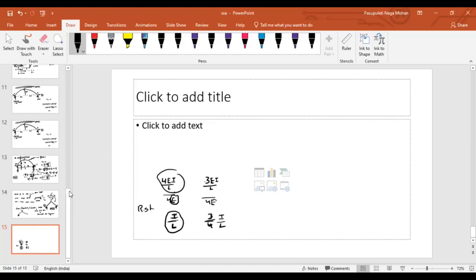I depends upon the cross section. E depends upon the material. In general, the material is constant everywhere; most of the time you will cast with the same strength of material at a particular level of floor. But the cross sections can change from one section to another.